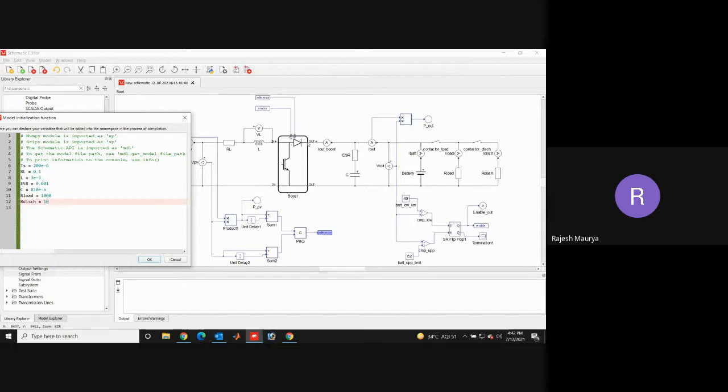See, first we are measuring the voltage across here, and we are comparing it. We have just given a limit. Whenever it drops below 49, the boost converter will be enabled and the battery will be in charging mode. Whenever it goes above 52, it will disable it, meaning it will give a zero signal at this Q, and it will disable this boost converter. That's the main motto of this part.